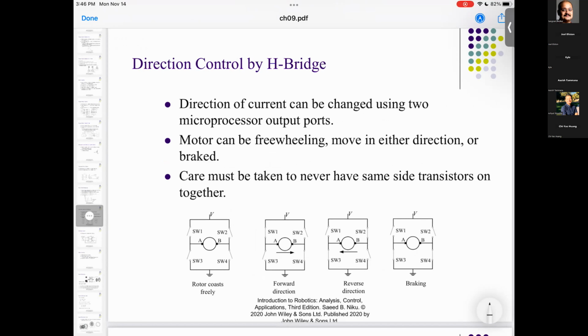Now, the next part is why do we need speed reduction? As we talked about, the power is going to be constant. So we have to manipulate either torque or the speed. If the speed increases, torque drops down. So with the help of the gear transmission, we control the speed and manipulate the torque.